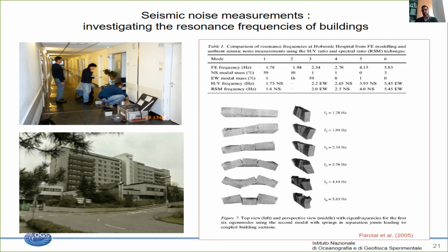So this is another way to use seismic noise, also to get information, at least on the resonance frequency of a structure. Recently, and I will show you later, we are also doing more. We look at the wave propagation inside the structure using a more advanced method, a little bit similar to what I showed you for the boreholes.